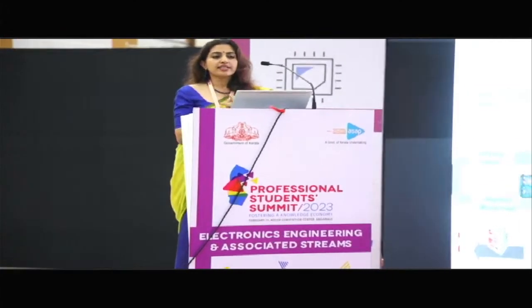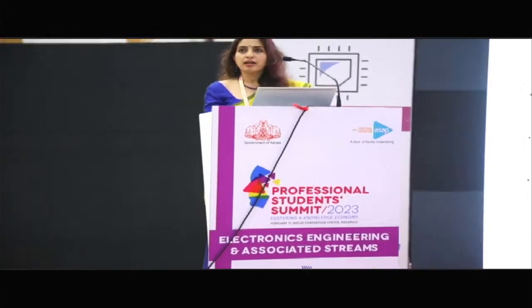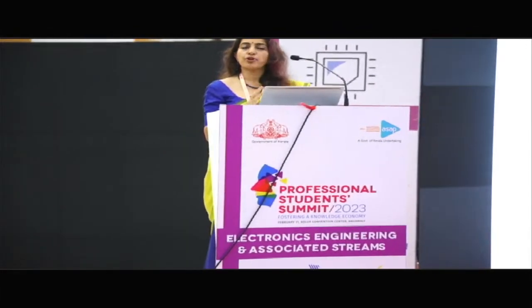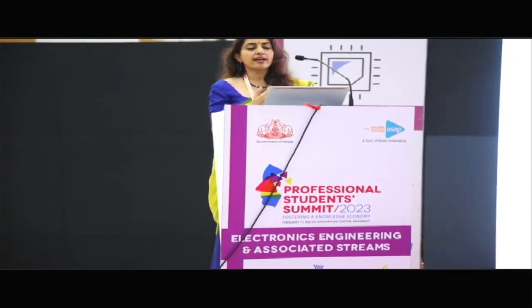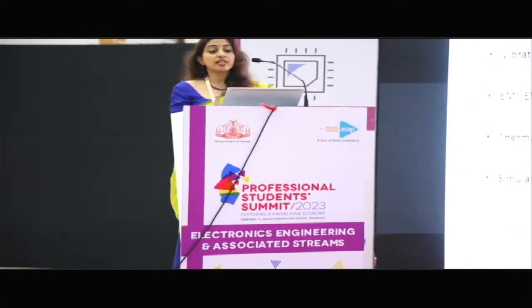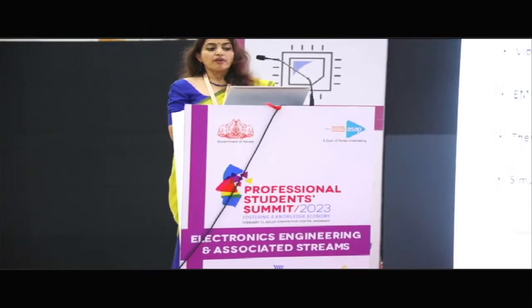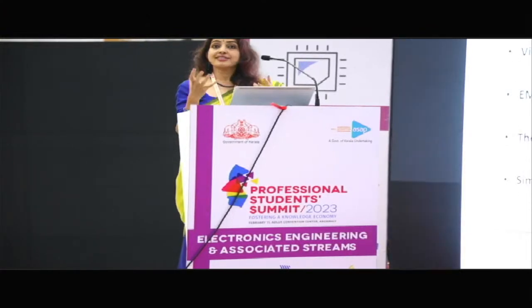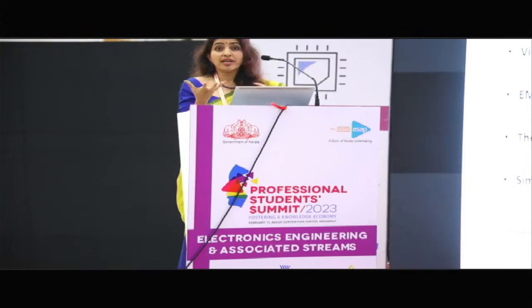Now coming to the tests for avionics packages. Normally in commercial packages we go only for the first point, functional test, maybe card level, module level and package level. So why are so many tests required here? These are called environmental tests. Vibration tests are very much essential, because the avionics package is sitting inside a launch vehicle, right? When the launch is happening, the solid booster is burning at a very high rate and sending shock waves through the structure.